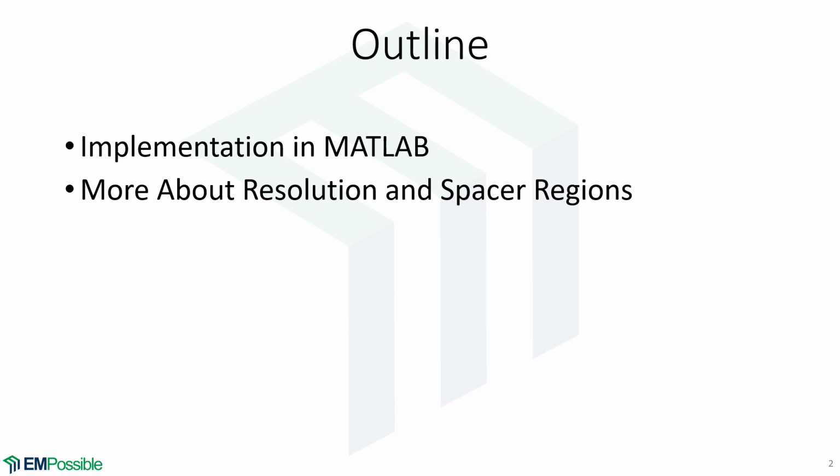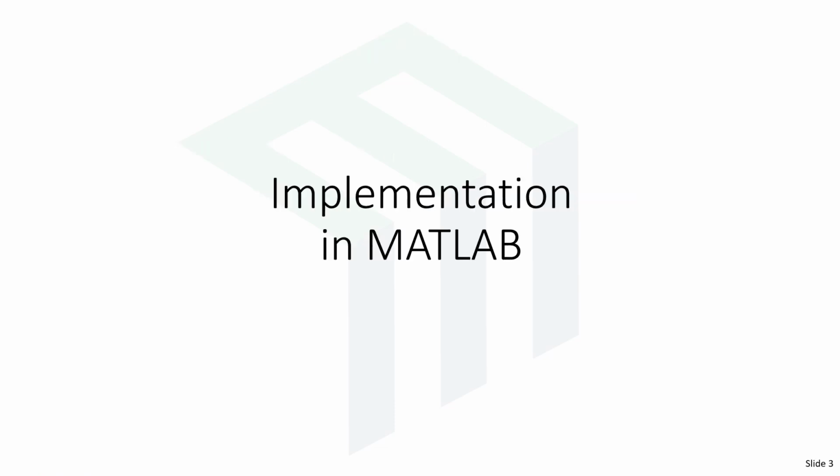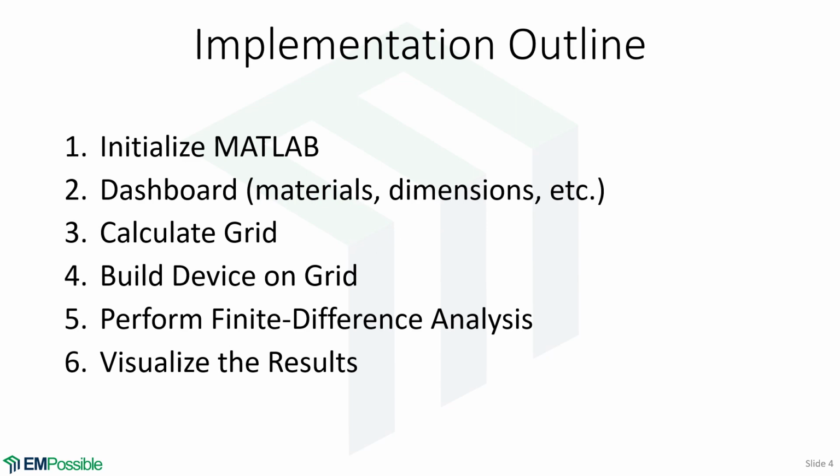So first we'll discuss implementing slab waveguide analysis in MATLAB, and then we'll talk more about resolution on the grid and what we're calling spacer regions. Implementation in MATLAB. So implementation of slab waveguide analysis goes very much like this.